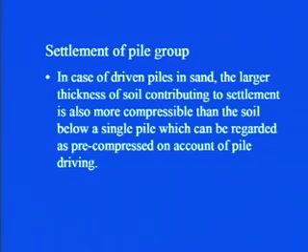However, what happens in case of a group of piles? Although the soil will be compressed within the group, if you see the group overall, the compressibility of the soil is quite high. That means it is highly compressible as compared to a single pile, which gets compacted while driving, which is not the case in a pile group.